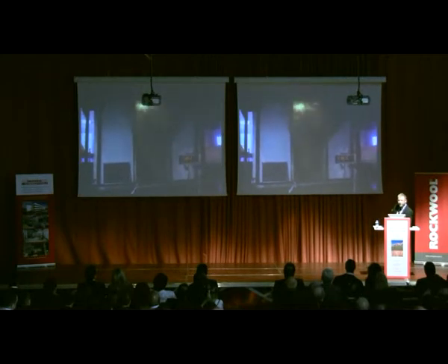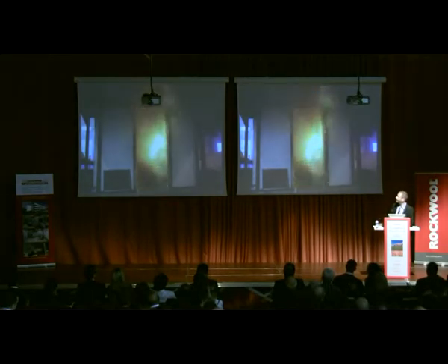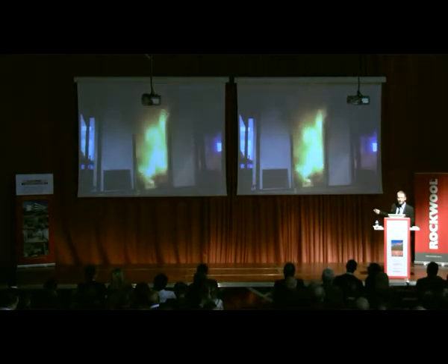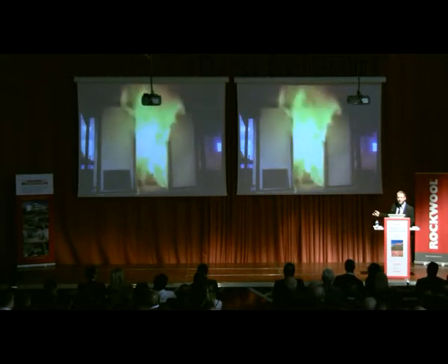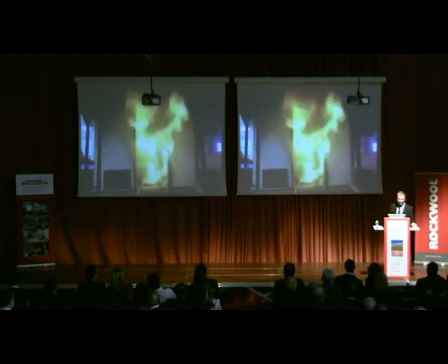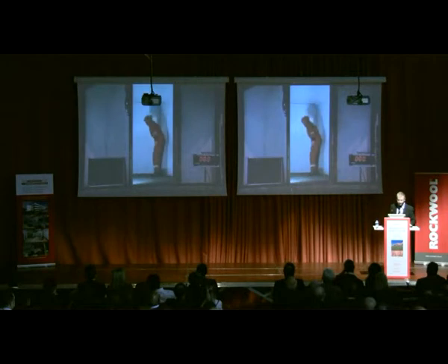And you may know that from polyurethane-based products, we can see most toxic smoke here. So this is the moment of flashover. And at this moment, we are not concerned anymore about what happens to construction. We start to be concerned to what happens on the other side. Because everything is burning inside, but the question is what happens to people who are supposed to be safe in other parts of the building. So you can see that it's not easy to extinguish, even though it's only 30 square meters of sandwich panel.